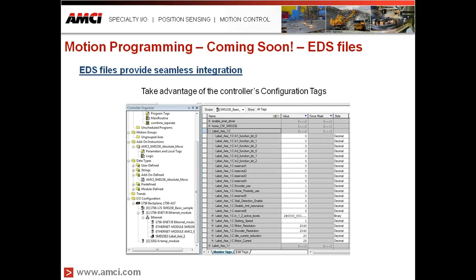And the other thing we're going to be doing in the EDS files is we're going to be taking advantage of the controller's configuration tags. If you remember in the generic setup, we weren't using those configuration tags. We were only using input-output registers. What we're going to be doing here is using these config tags, which will allow you to have a default configuration set up within your logic. You would use this to do your config data, and then you would only be using the output registers for doing command data.